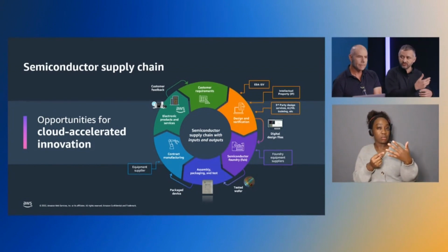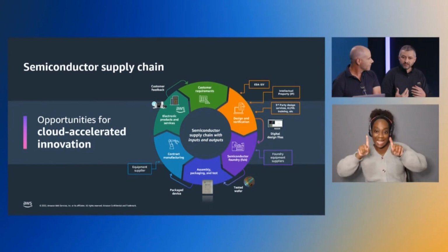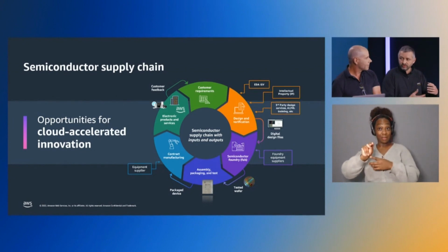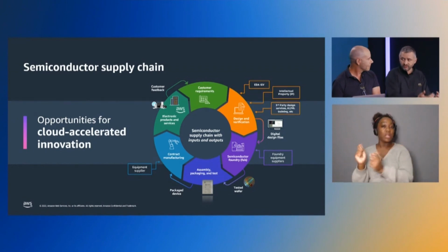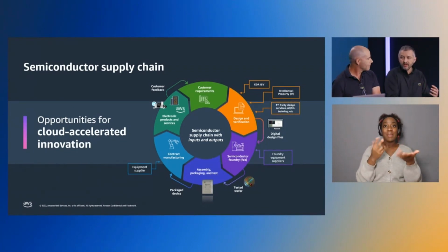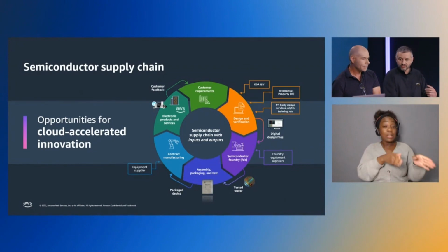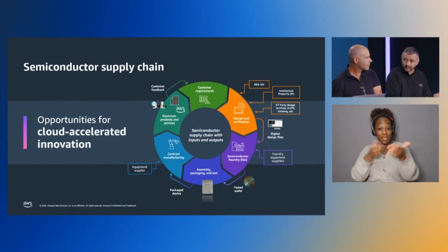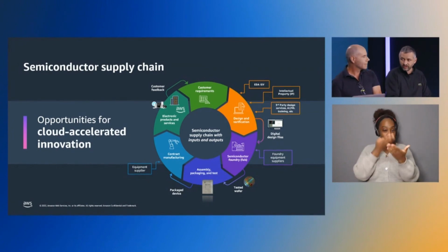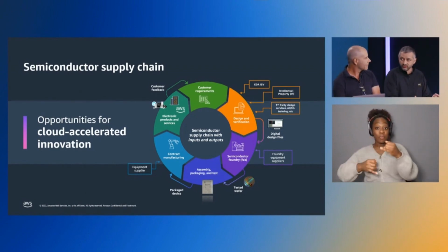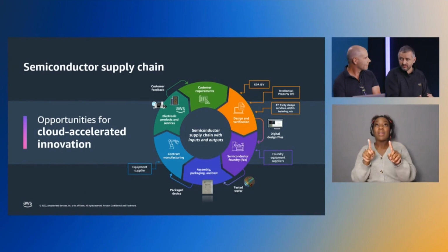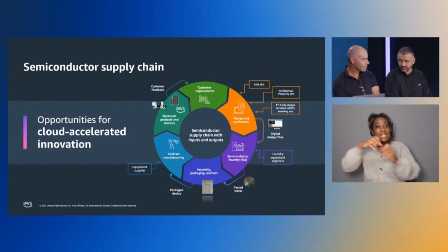And then after that, you actually start testing and validating that with simulation. And simulation, this is where you start to need more compute. Verification typically goes, I would say, depending on what you're trying to verify, there are at least three different categories of verification. Functional verification, obviously, the name implies you're trying to verify the functionality. And then there is another method called formal verification, where you're trying to prove mathematically that the design works, with some properties that you define for your design to behave to or not to behave to. And then there is also, depending on the content of your design, if you have analog or mixed signal circuitry, then that's where analog or mixed signal verification comes in.